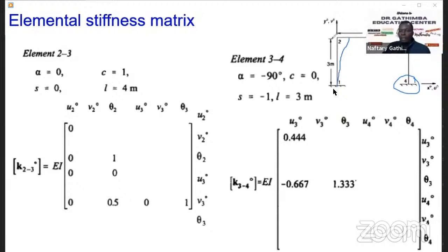But by the element, because the load is applied in this direction, we know that this member will not stretch, right? The axial stiffness is quite large. That's why you can comfortably say that the V3 vertical displacement at this node is equal to 0. And of course, the components at node 4 are known now because of the fixity.